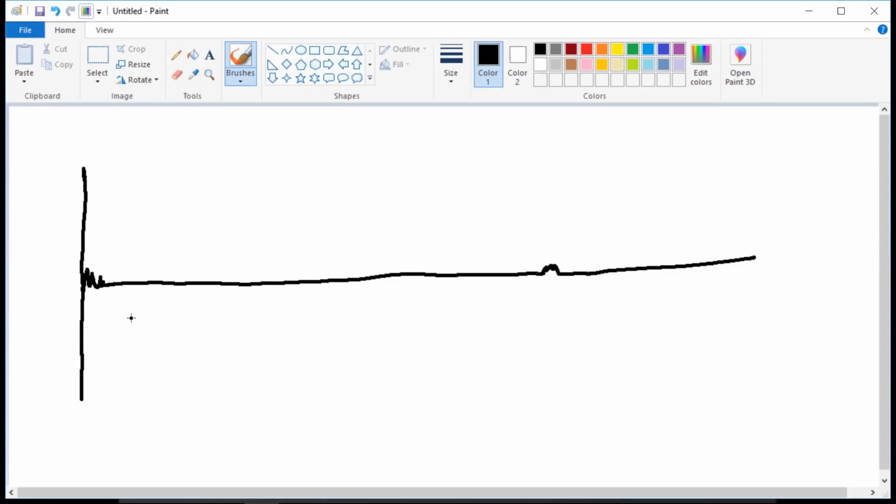The machine is telling you, and it's going to draw a line. This is the beginning of your conductor. That's the end of your conductor, and you've got this little hump right here that designates the end. It's going to show you footage: 504 feet. How can I confirm that this is the actual end and not the open?